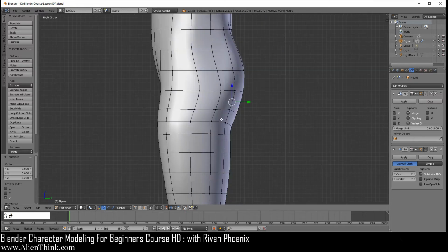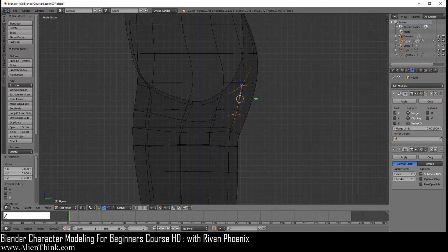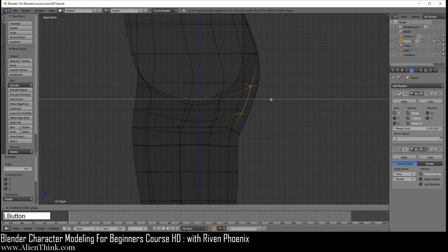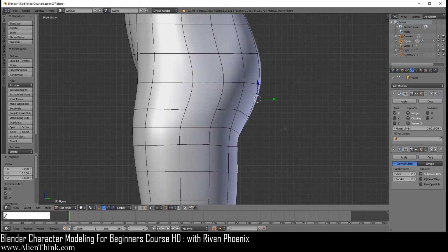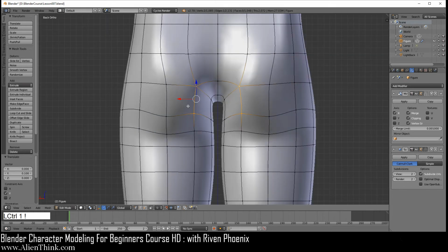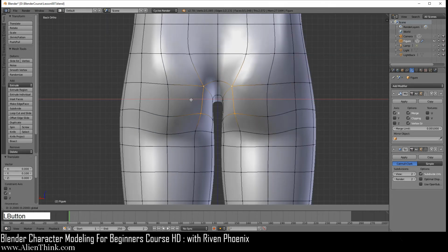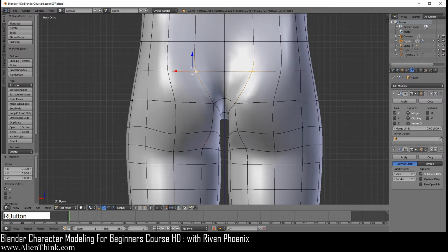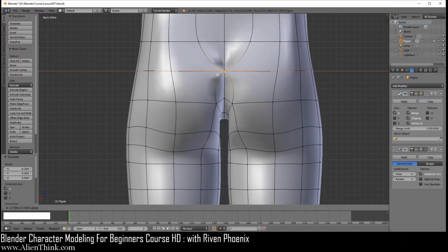You're going to go to your right view and you're going to press Z and you're going to come out 1 and then 2 over here and then rotate 1, 2, 3, 4, around 4. And here I'm just going to bring it out one more time and press Z. Just see what we're doing. And now go do Control 1 over here. Now take it to the right and just take it where it touches it and now go to the left 1 time like this. Same thing over here. Click on this, go to the right, touch it, and then bring it out 1 and then 2.